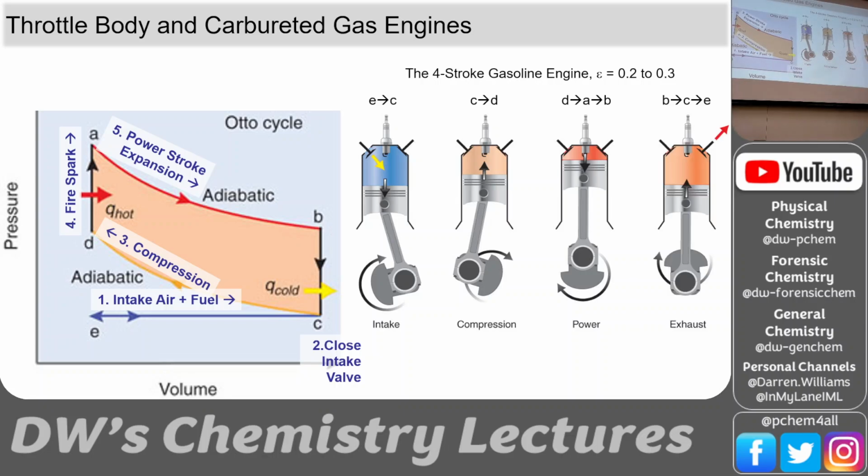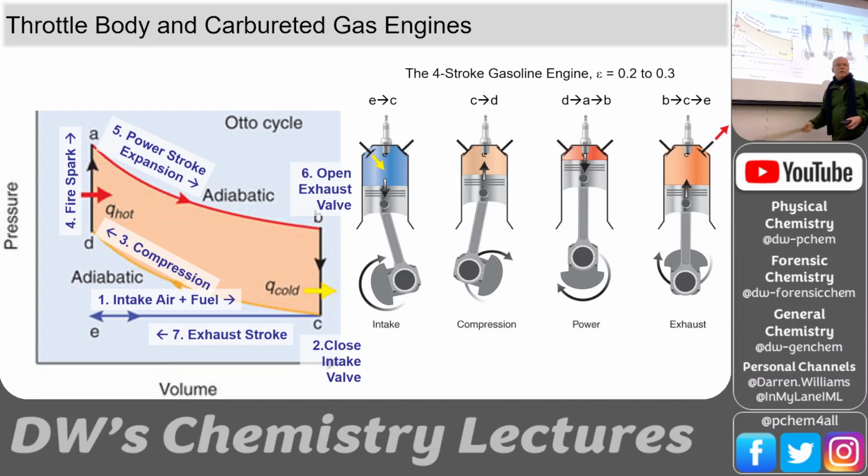Okay. And then when we get to the bottom, look what happens. We open the exhaust port, this valve over here, so that the combustion gases can be pushed out. And so then we have the exhaust stroke. So it comes over here. If we open that exhaust valve, what happens when you open that valve is, boom, the pressure drops dramatically. And then we burn a whole stroke just pushing the exhaust out. So the piston does this. It sucks in, it compresses the gas, it explodes and gives you the power stroke, and then it exhausts the gas. So the intake and exhaust happen at this low pressure part.